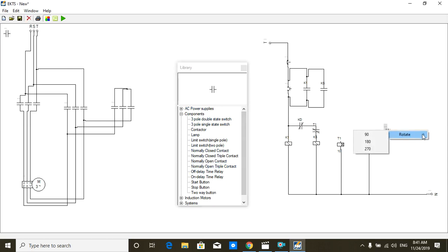This is normally open, this is the latch for the delta contactor, and this is for the timer contact. This is going through the timer relay, and this one is the latch of the delta contactor. So this is for the timer in order to energize the contactor, and then it will work on the latch. Okay, and this is the timer.